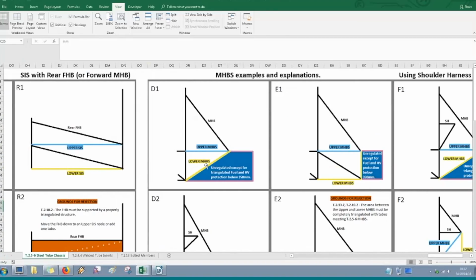One note is that any tubes, for example, rear suspension, if it's behind the main hoop brace support, that's free. As long as you don't have any part of the fuel system or the high voltage system in that area, we don't worry about those tubes. And if you do have the high voltage system in that area, that's going to be covered in the HV enclosure sheet.